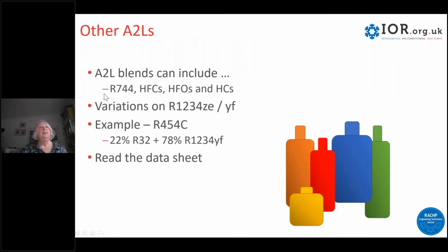So we have a lot of these, and they can include the HFOs, but as well as that, some of the blends have CO2 in, have other HFCs in, and hydrocarbons. One example is 454C, which is being used in some retail applications, and that's a mix of R32 and 1234yf.